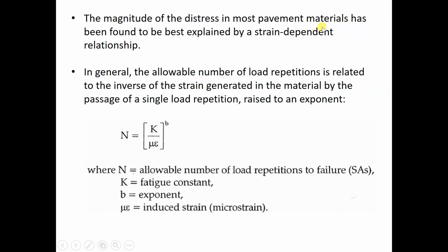So all the layers: the wearing course, the cemented layers, and the subgrade. For the pavement materials, if it's a granular layer, we don't consider the failure, because according to this elastic theory, if it's a deformation, it only happens at the subgrade.